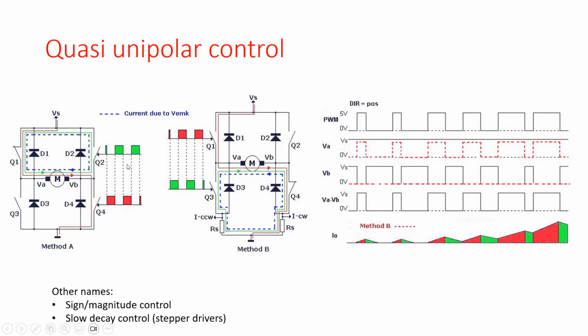When the PWM is 0, then the inverse PWM is high. So the voltage towards Q4 is negative, so Q4 is opened, but Q2 in that case is closed. So we see that the value of VB equals the power supply voltage because this switch is closed. So VB equals the power supply voltage Vs in that case.